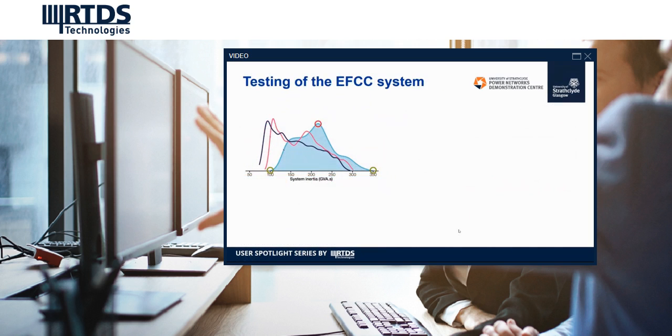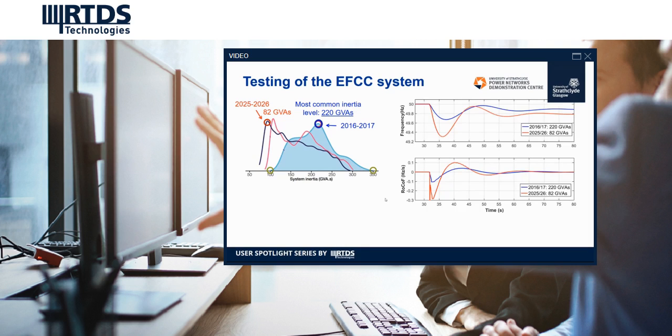We use the testbed for testing the EFCC fast frequency control scheme discussed before. Here are two scenarios. One is with a relatively high inertia of 220 GVAs, and the other has a relatively low inertia level of 82 GVAs.